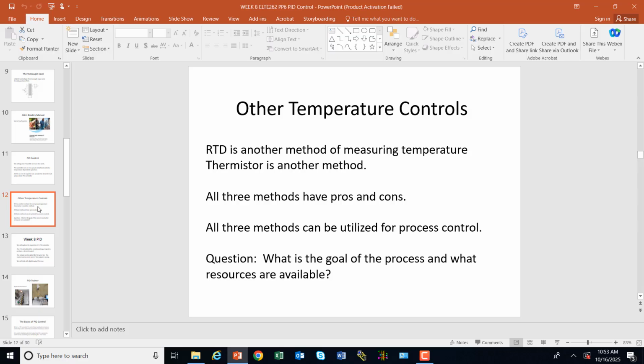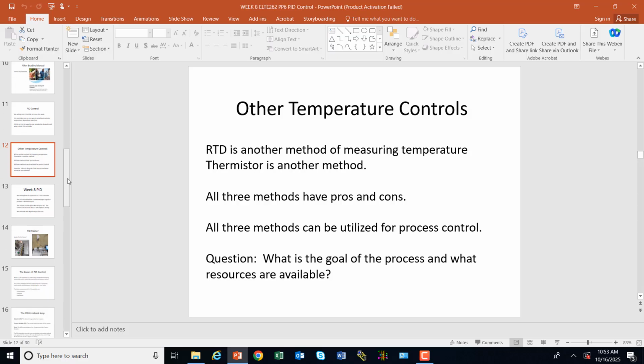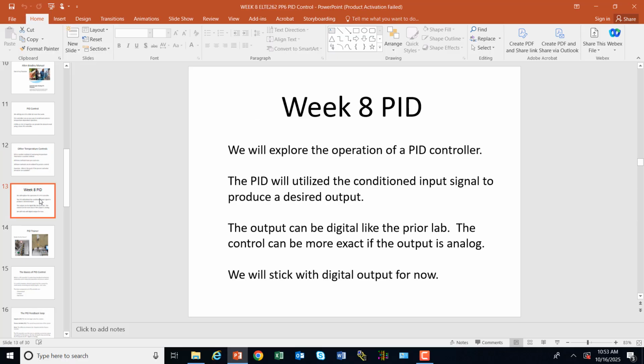Do you need very high accuracy? Do you need very high range? Is it low range? Is it serviceable by the technician, or do you need the controls engineers to hack into the PLC? There are just a lot of things going on here about what kind of control you want and you need, and then you're going to pick your process and your measurement to match that. And I'm sure that makes sense to you. We're just doing a little introduction here.